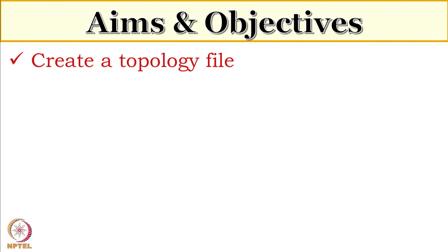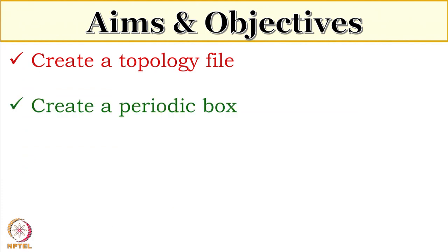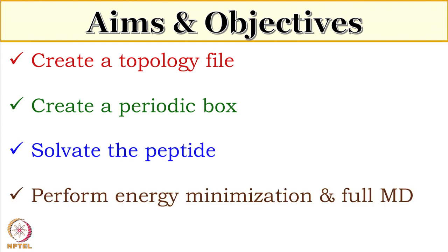So today we'll do the MD simulations of S peptide. First, we'll create a topology file from a PDB file, and then we'll create a periodic box around the S peptide. We'll also solvate it, and then we'll perform energy minimization and full molecular dynamics. After that, we'll analyze some of the properties of the S peptide using the trajectory.